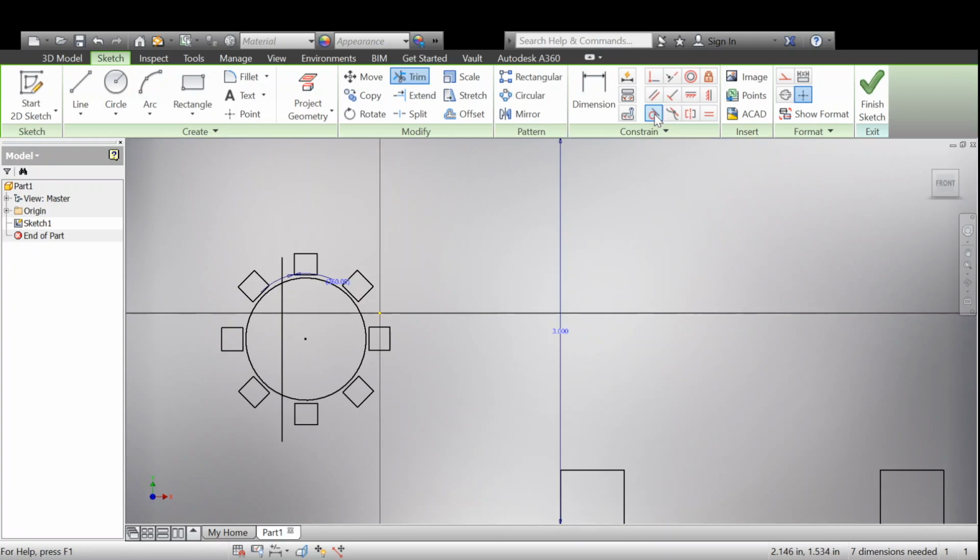This is probably the most powerful part of all of Autodesk here, the constraints that exist. So you could have tangency, you could have one that does what's called a smooth curve to smooth it over. In this case, it looks like a symmetric constraint. Here we have some sort of equality constraint, making two things equal. Here we're going to have a horizontal or a vertical constraint and keep something vertical or horizontal always.